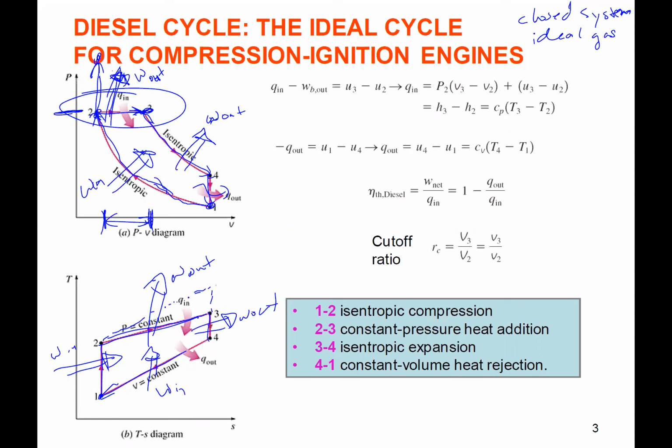All right. So for that heat addition process, since it's a closed system, we have our closed system COE. For that heat addition, we have that work term also and the heat, right? But because the work is at constant pressure, the integral of PdV is P times delta V. Pressure we can take out of the integral. We can combine these two terms, the change in internal energy and P delta V, and we get change in enthalpy, or Cp delta T.